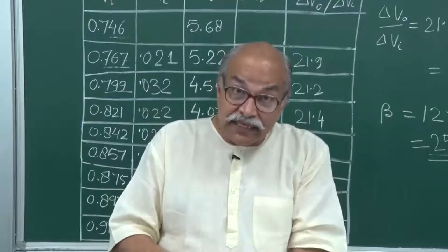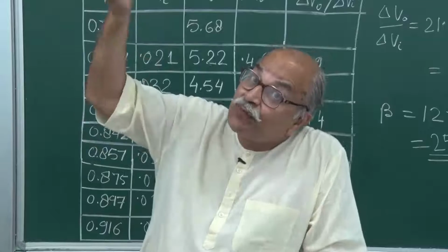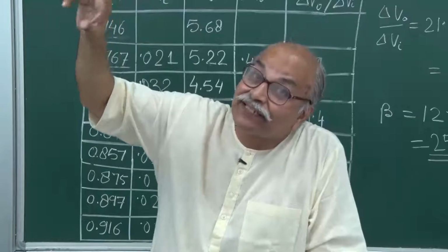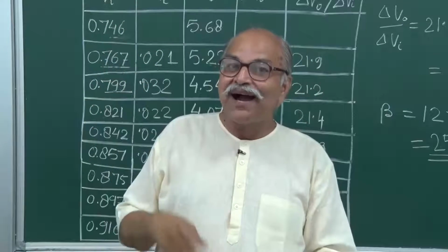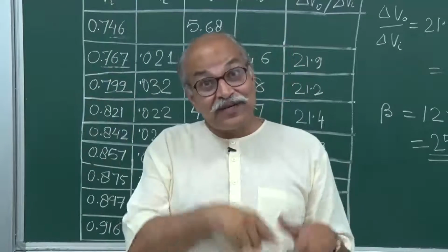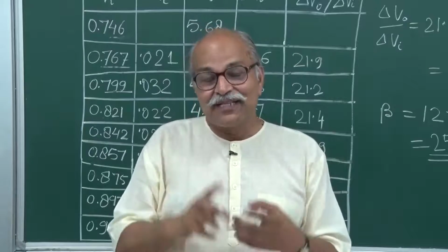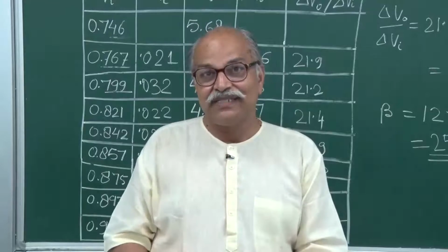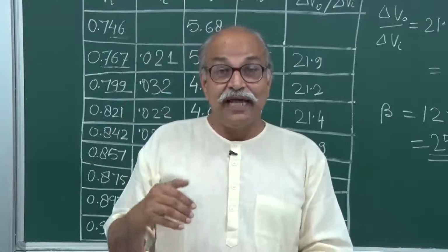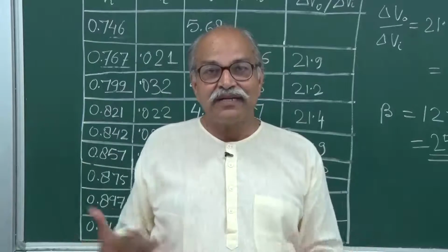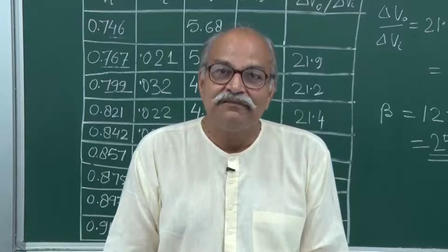So you are switching in the base circuit, and what we are controlling is the output. So the switching is appearing there. You are doing something here and the result is appearing there. So you are controlling a high current circuit from a low current circuit, and that is the benefit. That is how that switching takes place, and that is why a transistor is used for switching. And in digital electronics, the switching from high value to low value at a faster speed is very, very important, and all these things make the transistor a useful device for a switch.